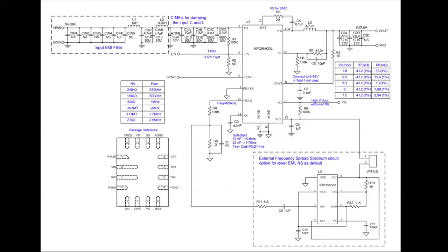In a switching circuit, in a switching device, the most important things are the switching node. Remember, it is where you are creating harmonics and usually ringings. This is a high dV/dt node. It's a strong electric field area and is connected to the inductor.